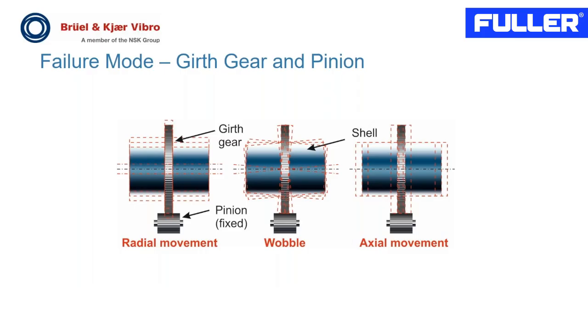This can result in improper gear meshing, variable gear tooth root clearance, and incorrect pitch circle alignment. This creates stress, and the stress will eventually lead to premature wear and failure. And moreover, as the gear teeth wear, this increases stress even more. And then, of course, lubrication problems can also accelerate the wear.